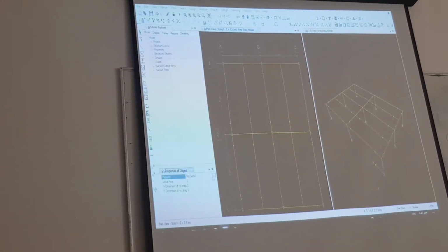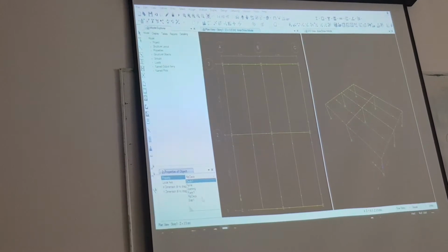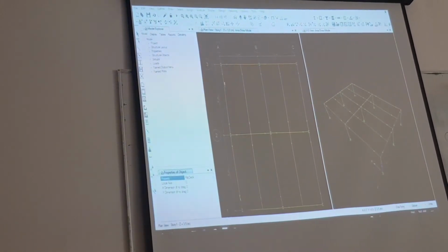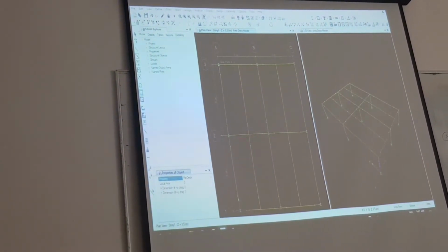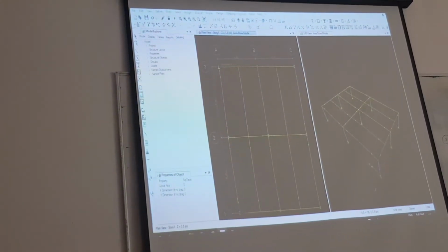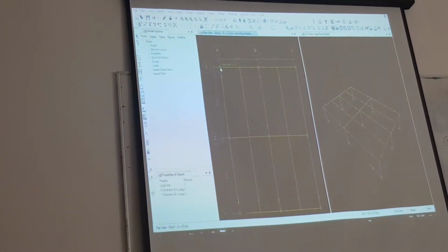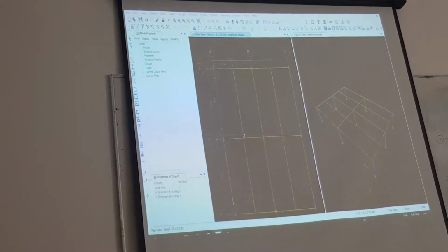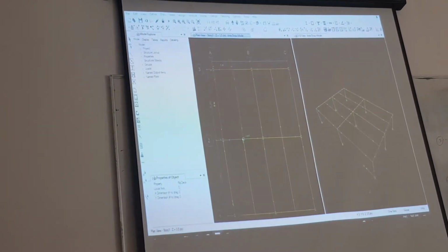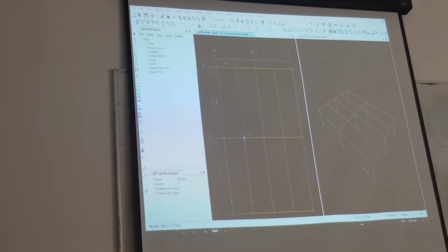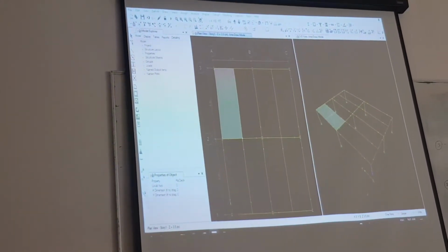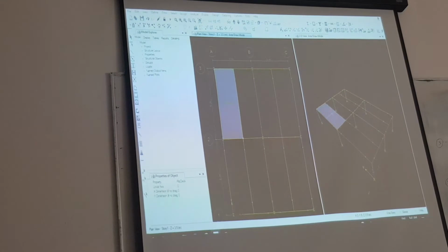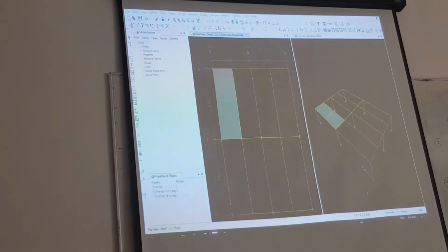Again, you are going to select the rib deck property, the one you have defined. So first, click on the first point and do not release your mouse button and simply click on the opposite joint. Here you have defined your rib deck system, okay?